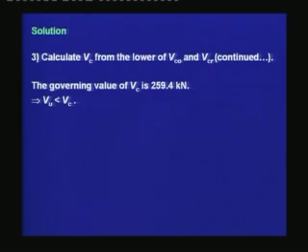Thus, what we find is that at the face of the support, the Vco, which is the shear required to generate a web shear crack, is much lower than the shear required to generate a flexural crack and to change the flexural crack to a flexure shear crack.